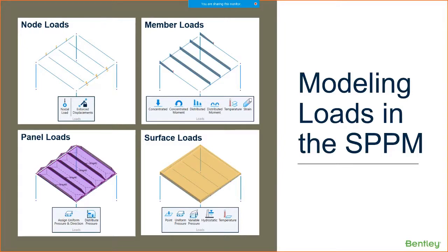The load can be distributed based on a one-way or two-way distribution, and I think of this load as the same type of load system as, say, a floor load in the analytical modeler, where we can distribute that load to the supporting members, and you can go ahead and enter it in terms that you've probably defined a surface load as far as your engineering project goes.